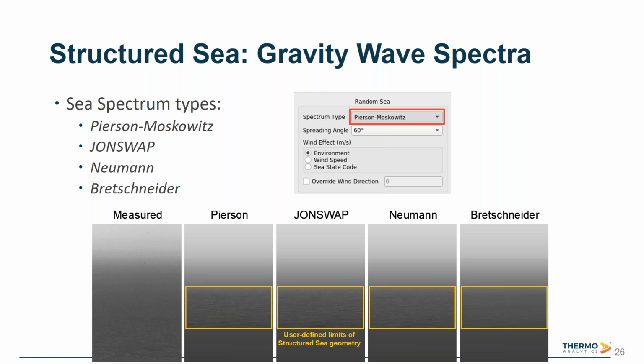And the Bretschneider is an average width spectrum developed for the North Atlantic and assumes infinite depth with no swell and unlimited fetch. It's a 2-parameter description based on model frequency and significant wave height. This is more useful for modeling wind-driven seas rather than swell.